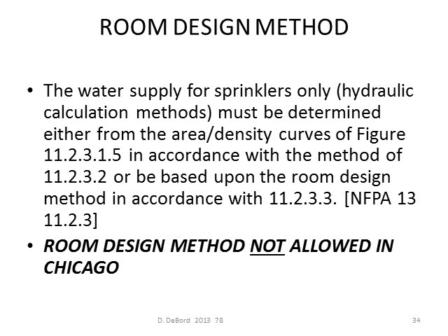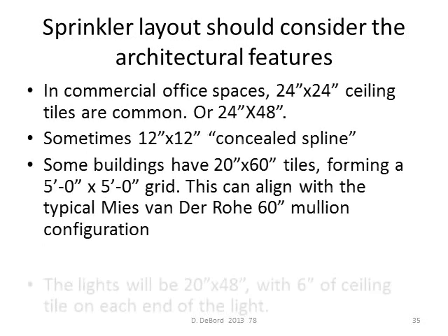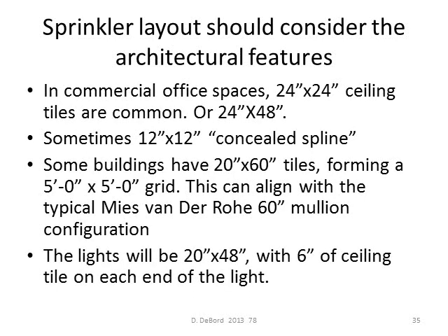Just a note about the room design method. The water supply for sprinklers only must be determined either from the area density curves provided in NFPA or based upon the room design method in accordance with NFPA 13 11.2.3.3. Again, room design method not allowed in Chicago, but we wanted to mention it. We don't only work in Chicago.